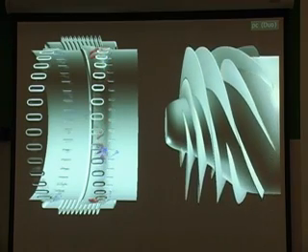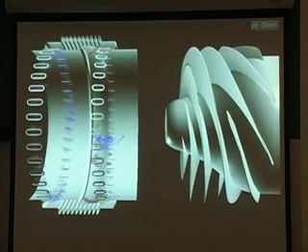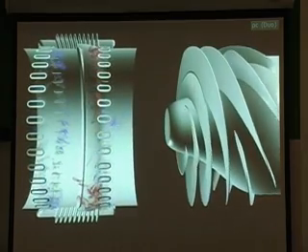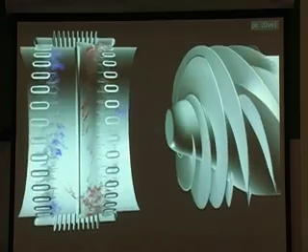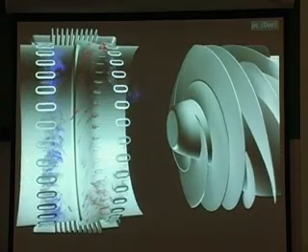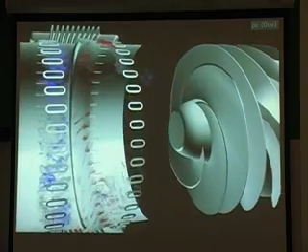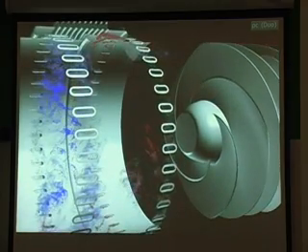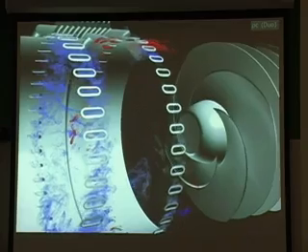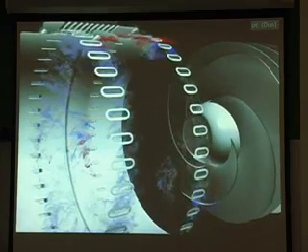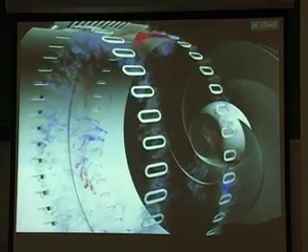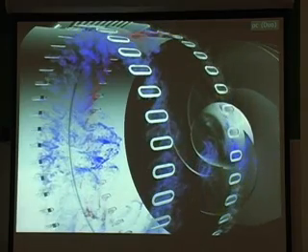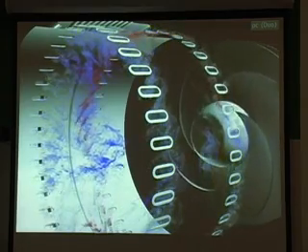The one major point of this study was to try to understand the causes of cracks that are seen in these two rings of holes. These are actually ports that are put into this flow liner to retrieve welding debris after the joint is formed. So they're not, or they initially weren't designed with flow in mind. But in use, the liquid hydrogen actually flows in both directions, it turns out, through these holes.